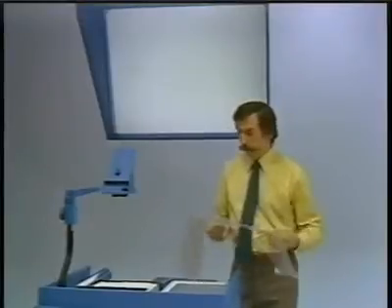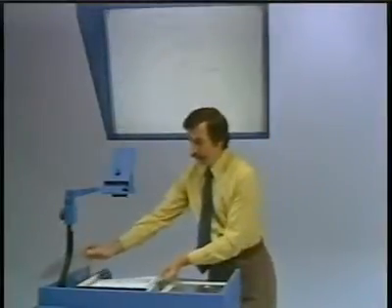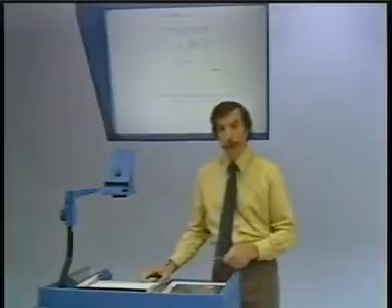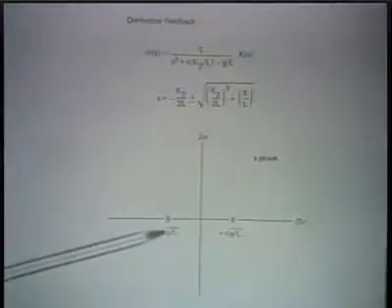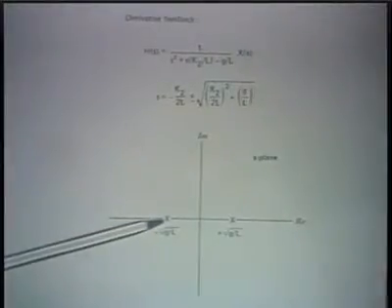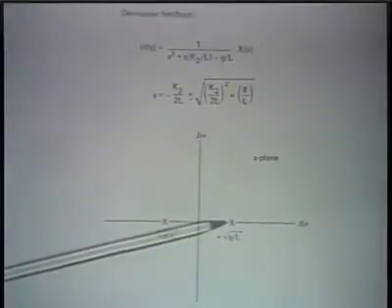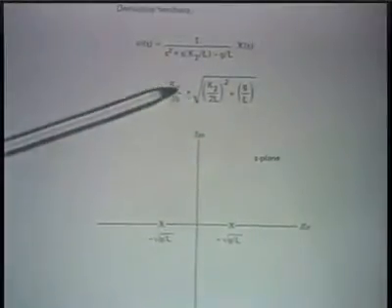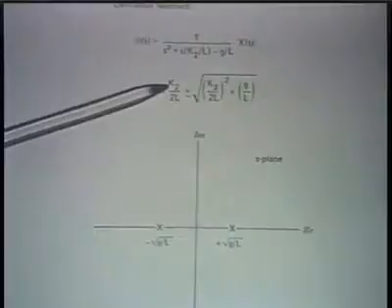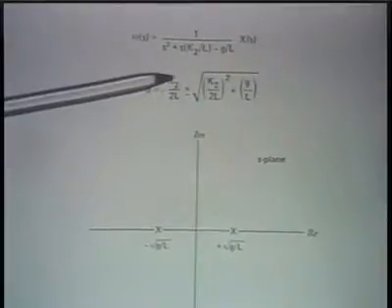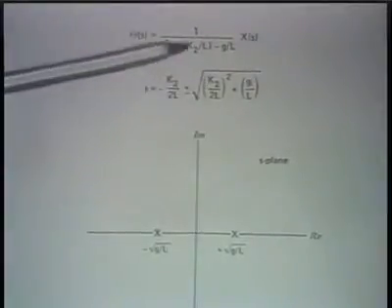And first, once again, we have the basic open loop poles. And the open loop poles consist of a pole in the left half plane and a pole in the right half plane, corresponding in this equation to K2 equal to 0. That is, no feedback in the system.